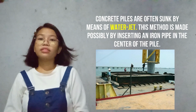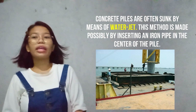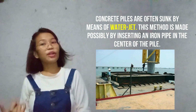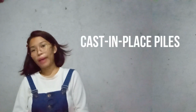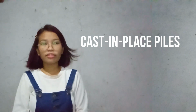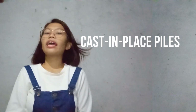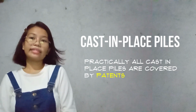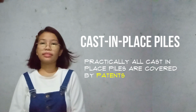Concrete piles are often sunk by means of a water jet. The method is made possible by inserting an iron pipe in the center of the pile. Cast-in-place piles are constructed in the ground in the position they are to occupy and are often reinforced. Practically all cast-in-place piles are covered by patents.